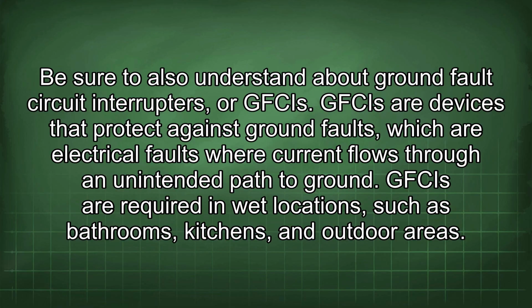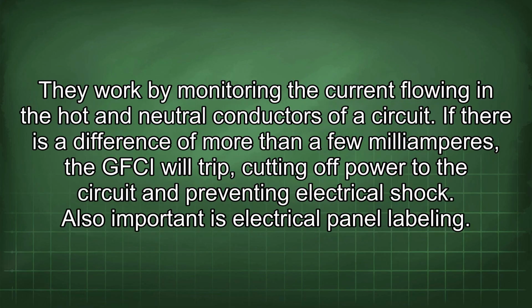GFCIs are required in wet locations, such as bathrooms, kitchens, and outdoor areas. They work by monitoring the current flowing in the hot and neutral conductors of a circuit. If there is a difference of more than a few milliamperes, the GFCI will trip, cutting off power to the circuit and preventing electrical shock.